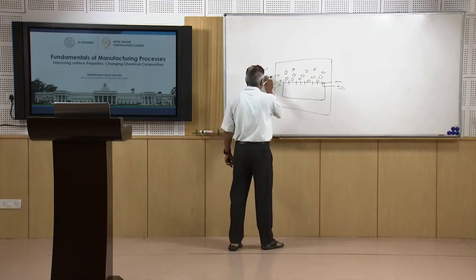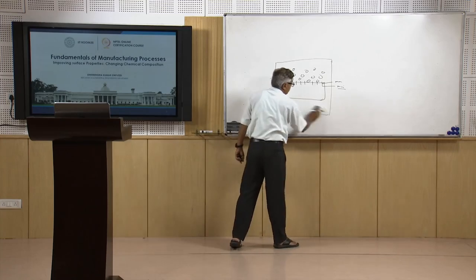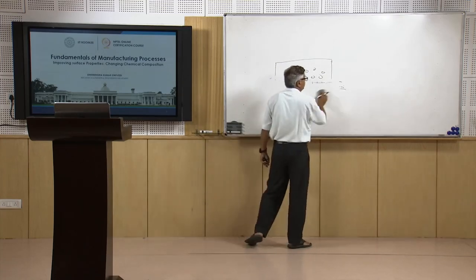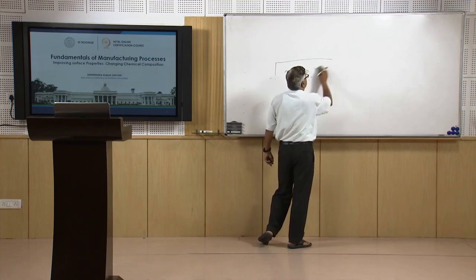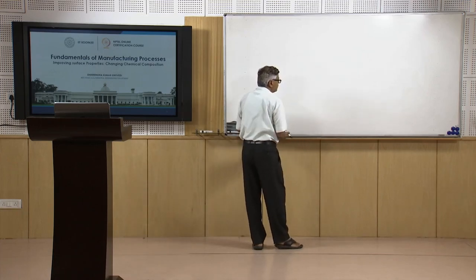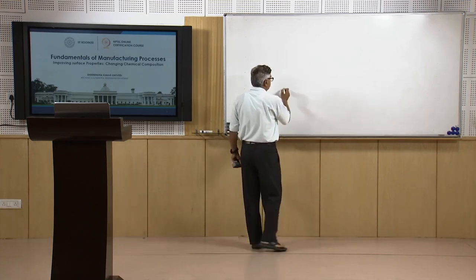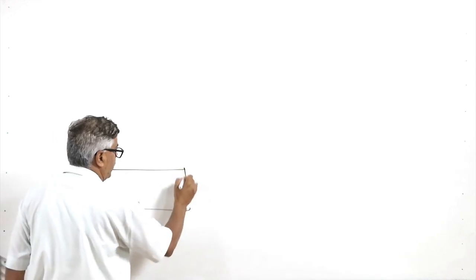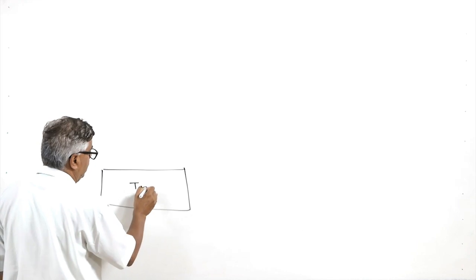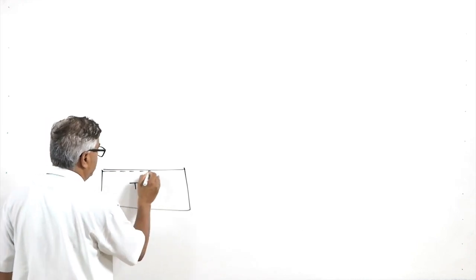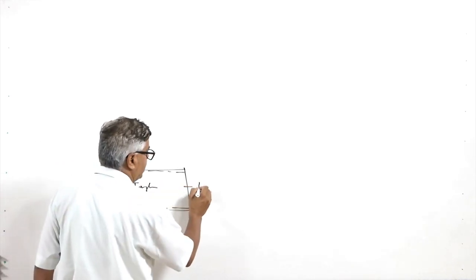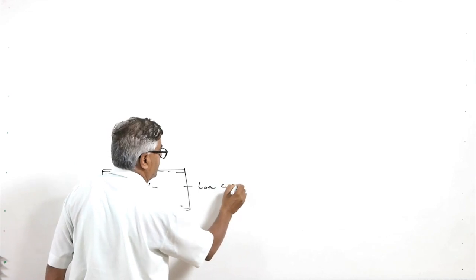Carburizing is one of the most common process which is used, and as name appears, in carburizing, carbon rich environment is created all around the component for introducing the carbon near the surface of the component. So, which type of the components are carburized, that is what is to be seen, like the components wherein we want that core is tough while surface is hard. So, this kind of the properties are offered by the low carbon steels.